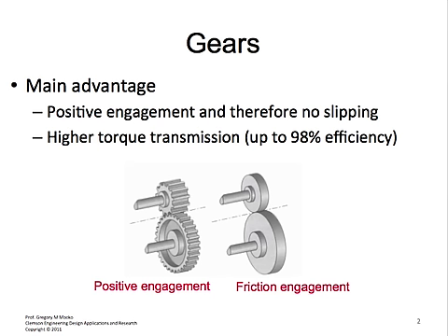That's why we have teeth. Certainly the kinematics of a gear are the same or similar to the kinematics of two cylinders rolling on each other without slipping. Gears are efficient. Certainly spur gears are the most efficient, with about 98 to 99% efficiency.